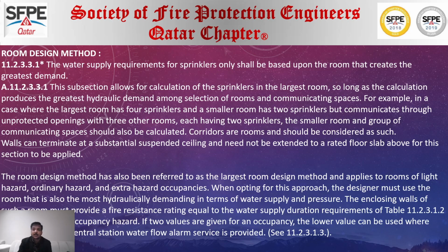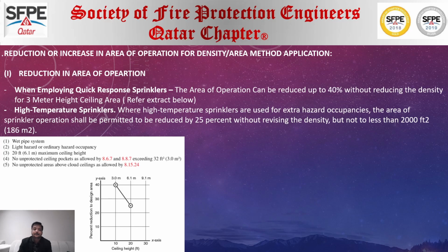It should be used only if you have a series of rooms with a fire rating provided for all the rooms. If you are not providing fire ratings for any one of the rooms, then the room design methodology cannot be used. Another thing mentioned in NFPA 13 is reduction and increase in area of operation.